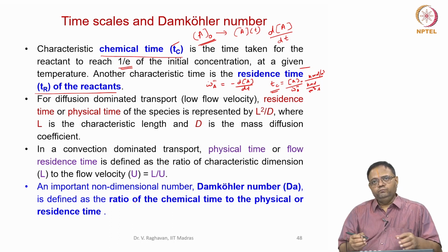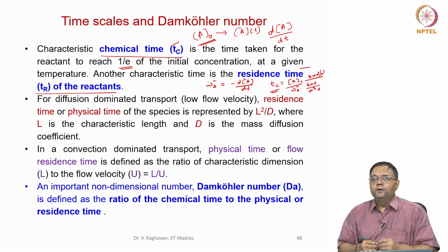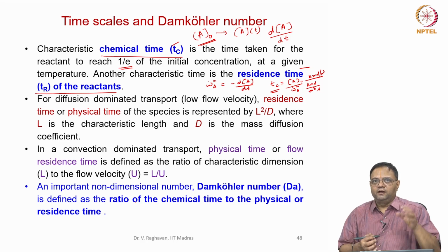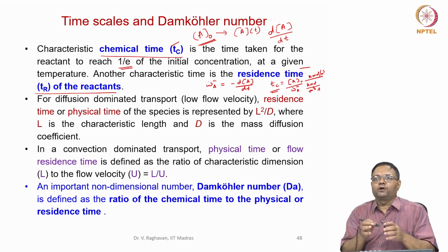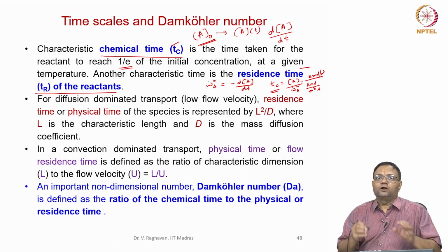So that means even when the mixture is formed and the mixture is flowing at a velocity, the mixture at a particular location may not reside up to a given time where the chemical reaction is complete. So the residence time means that the mixture has to stay at a particular location until the chemical reaction time completes. So that is called residence time.